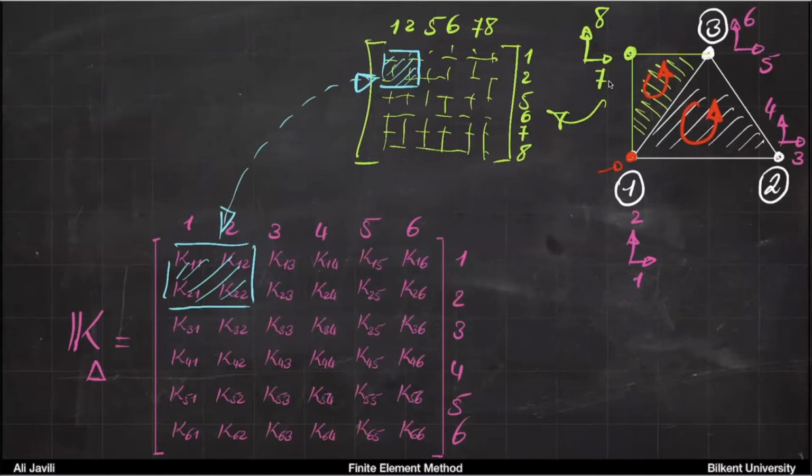So what I'm trying to say is that as soon as you understand how the stiffness for one element works, then you are done. You have nothing more to do compared to what you had done already for a one-dimensional FEM or for a truss structure. The assembly process is exactly the same assembly, the same subroutine in your code.